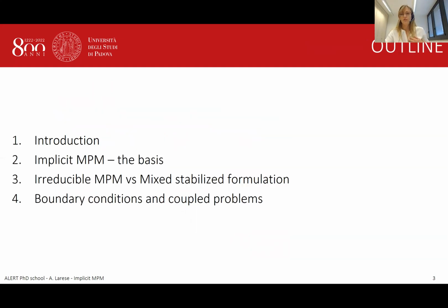So the presentation is structured as follows. I will follow quite a lot the lecture notes. I will first motivate why I ended up using MPM and why I wanted to try this new experience, and then I will explain the first steps we have done in this new world. We are new babies, so you won't see amazing videos, but basic formulations. I will also spend some words about formulations: irreducible MPM versus mixed formulation to overcome locking problems, basically volumetric locking problems that appear when you deal with incompressible materials. In the last part of the presentation, I will present the work we are doing on coupling MPM with other techniques, basically FEM.